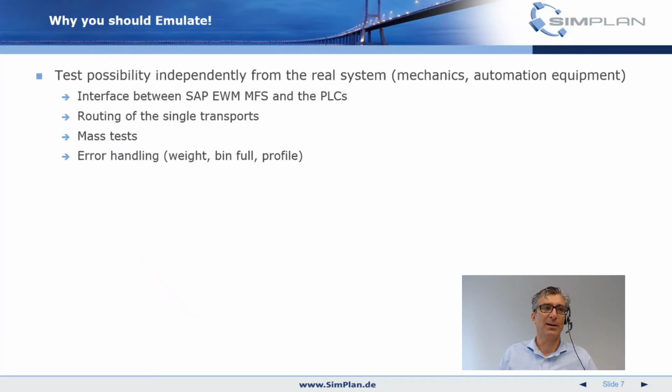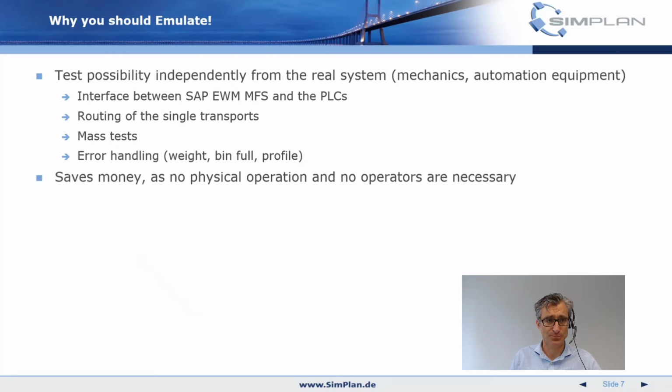you also have the possibility to test errors, which is very hard to do in reality, because how do you trigger an error? Even when it's a test run, it's very easily done in the virtual world. So trigger a weight failure, bin full failure, or a profile failure, and then you want to see how the material flow controller reacts to these kinds of errors, if they are handled correctly, or if the logic is not implemented well. It saves you a lot of money, as you do not need to have any physical operation.